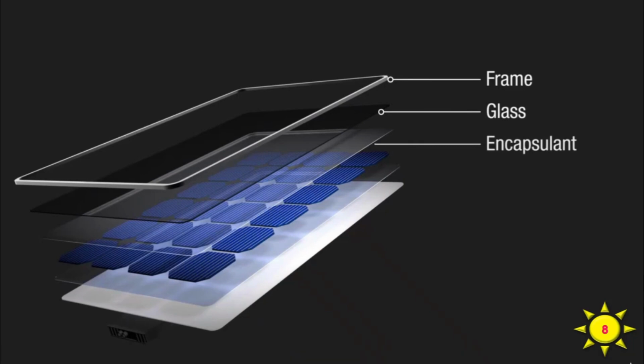Its structure is a transparent polymer layer, which is usually made of EVA. The primary purpose of this component is to hold the solar cells in their proper place and provide a robust shield against moisture and external vibration. In the next layer are the solar cells themselves. It keeps the solar cells in place, protecting them from moisture and vibration. The next layer contains interconnected silicon cells, which convert solar energy into DC electricity. This layer is the heart of the solar panel.